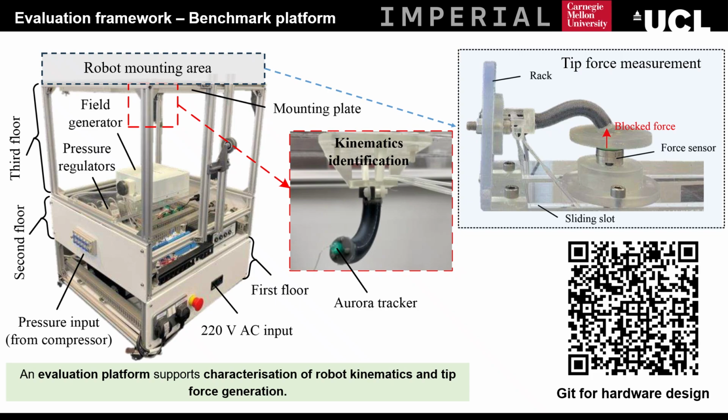To validate the forward kinematics and tip force generation models, and further to evaluate robot's performance, we built a dedicated benchmark system. It includes a kinematic tracking setup using Aurora or other cameras, a force measurement rig to characterize the robot's tip force. The platform accommodates manipulators of different lengths and diameters. In combination with the analytical modeling framework, the complete modeling and evaluation framework of soft manipulators is achieved.